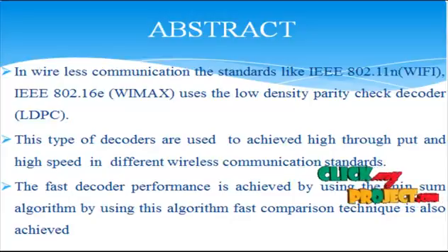This schedule efficiently utilizes the layered LDPC decoding with minimum pipeline stages, and this project presents the architecture of a block-level parallel layered decoder for irregular LDPC codes. This code can be configured to support various block lengths and code rates in Wi-Fi standard communications. The system presents efficient comparison techniques for both column and row layered schedules, and high speed circuits to compute the two minimum values from multiple inputs required for row layered processing of hardware friendly min-sum decoding algorithms.